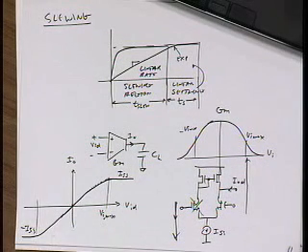And really the small signal model of the circuit is not a very good model, because the small signal model assumes that you have loop gain. You've got GM in a feedback, lots of loop gain, and so this feedback amplifier is driving the error term on the input to 0. Well, no, you don't have that. What you have is an amplifier that's dead, and its output is just being charged by a constant current.